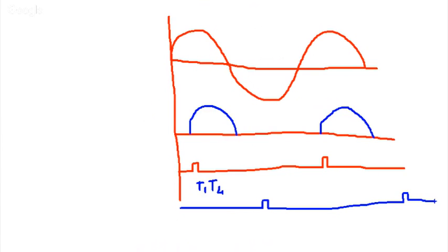For this case also, the thyristor will be fired like this, and here again you will get the firing. So this is the half bridge rectifier, pulsating half bridge. In this case you are firing your T3 and T2, and it has to be repeated after every 20 milliseconds.